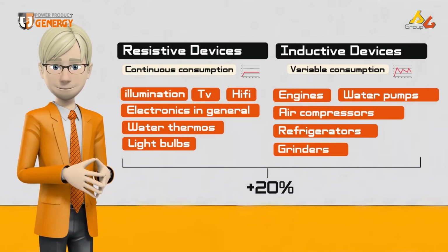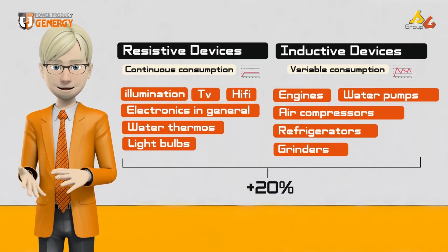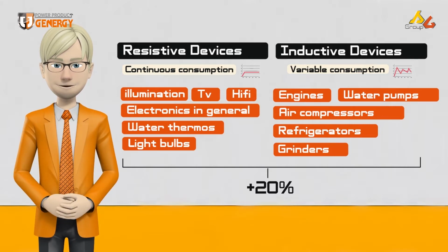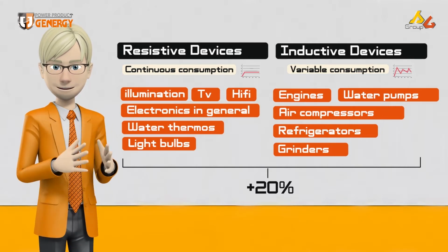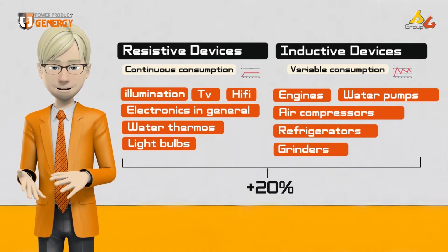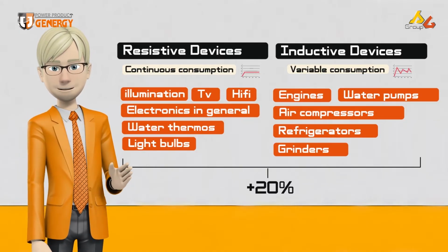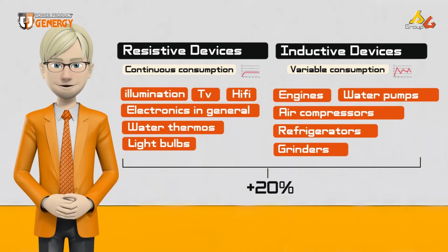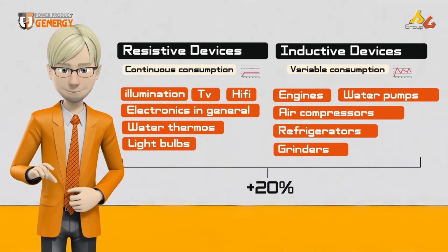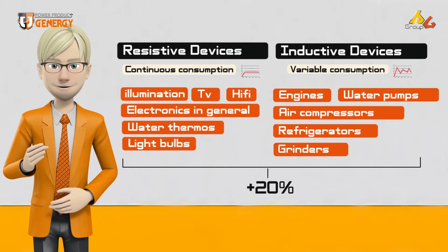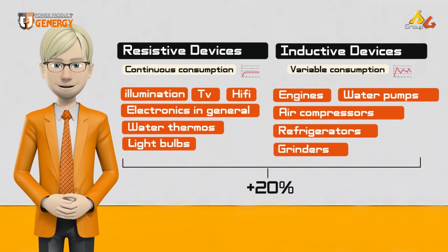Remember to always check the power rating of a generator on its datasheet. It is quite a common mistake to confuse the name of the generator with the real power. Do not assume that the generator Mod Pepito 4000 is a generator of 4000 watts of power, because it is quite common to use this data to confuse customers.